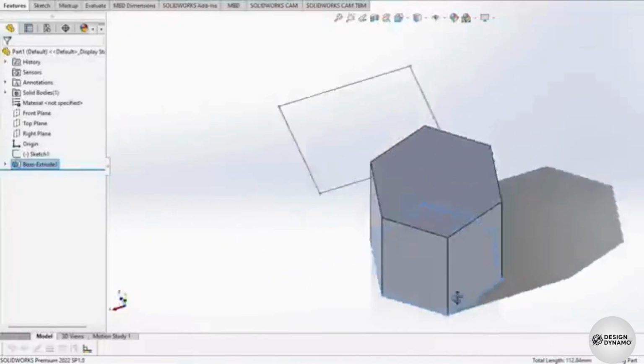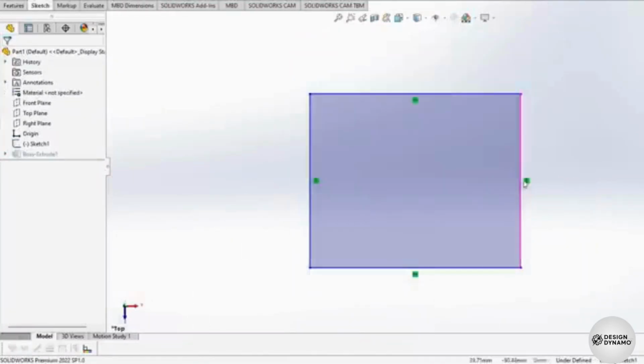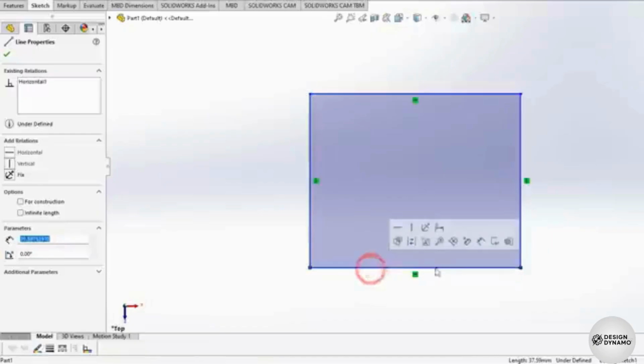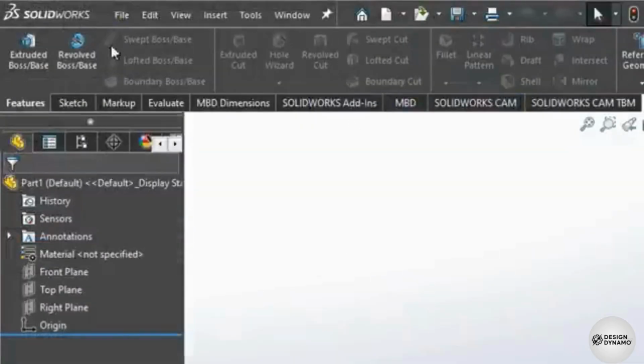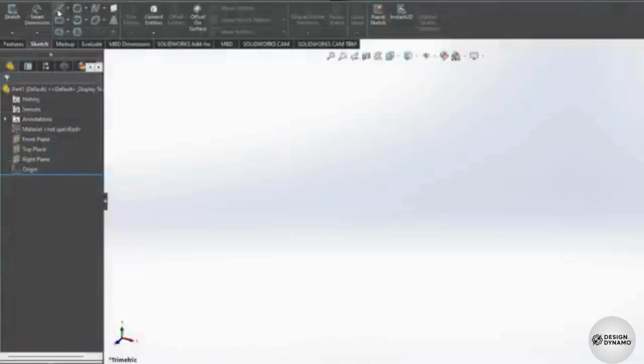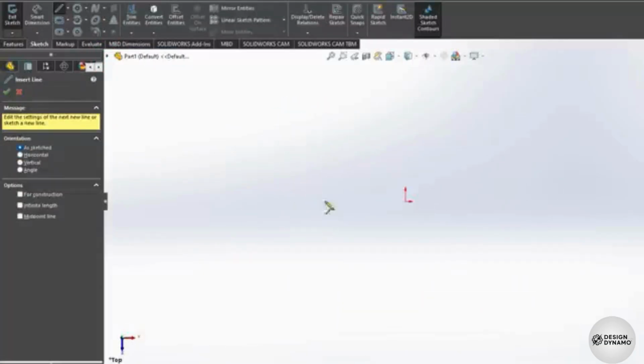In a part project, you can drop 3D objects called features and 2D drawings called sketches, starting from elements like lines and curves called entities. Let's start making 2D drawings. From the Sketch section on top, you find all the tools to 2D draw. The first time you enable any tool, you have to choose the plane to draw on, from either the Preview or the Quick Selection list on the left. We suggest to always draw 2D objects on the top plane, which represents the ground plane.